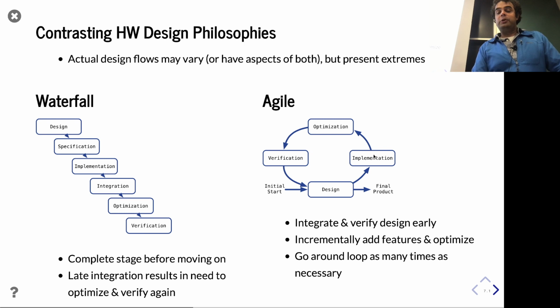And so you need to automate everything so that you don't flinch about doing this over and over again, right? So if you can go from Chisel and it's automated to get pushed into Verilog, to get pushed into your various design tools, and get pushed through your entire flow, run your verification suite. If this is all automated, you don't mind doing this over and over again, right? And heck, this might be a lot of compute, but you know what? Put computers to work. Make tools do the work. That's one of the themes in this course, right? So automation can help you there.